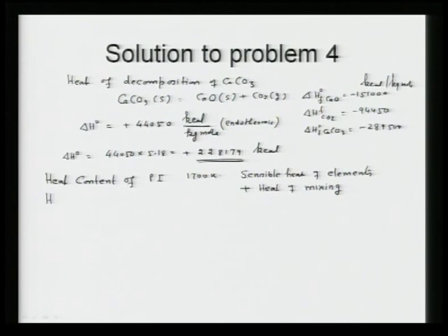For the given temperature, H 1700 minus H 298, I am giving you these values for iron, carbon, manganese and silicon: for iron 13090, 6610, 17480 and 20,756. Mind you, they are all in kilocalorie per kg mole. So, I can now calculate the heat content of pig iron, as I know the kg moles.